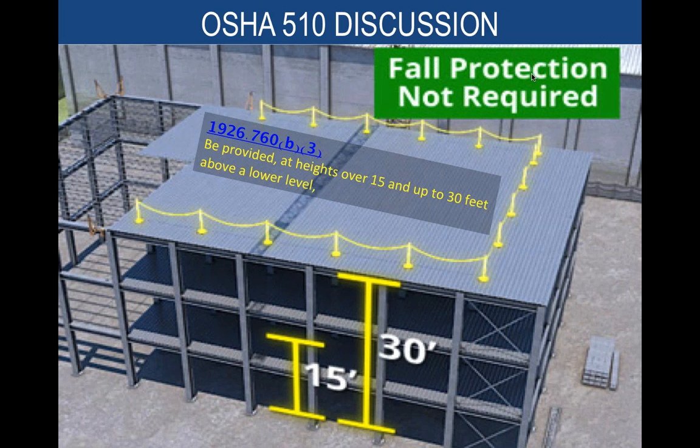Practices like not walking under a load, always wearing a hard hat, using toe board screens and guardrails to prevent fallen objects from striking those below. We'll talk about that in a moment. I'm going to show you how to pull that up again in the OSHA standards, okay? Also using safety glasses, goggles, face shields around machines or tools that might have flying particles or flying projectiles.